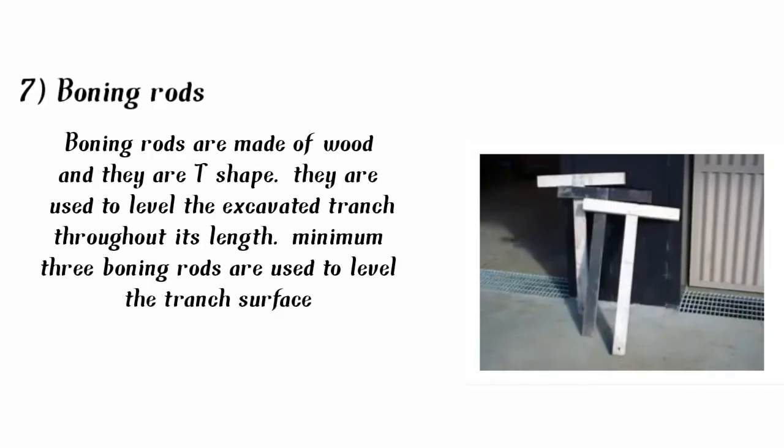Number 7. Boning rods. Boning rods are made up of wood and they are T-shaped. They are used to level the excavated trench throughout its length. Minimum 3 boning rods are used to level the trench surface.